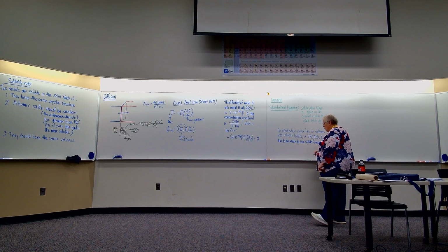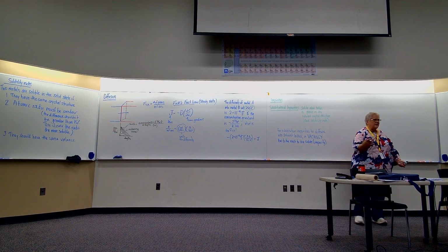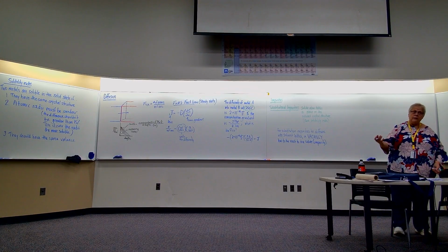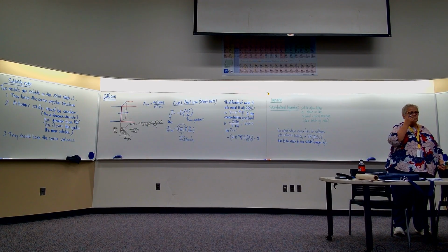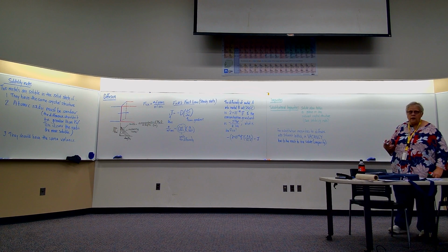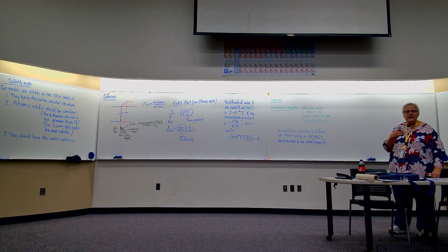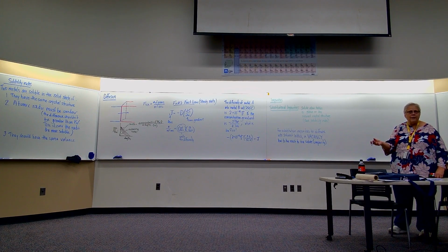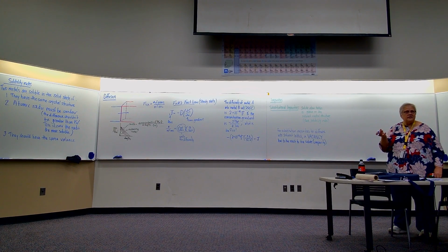So all these atoms are moving around and all the vacancies are moving around, and I've got my impurity atom waiting for an opportunity to diffuse in. And that can only happen when a vacancy comes available for it to jump into.